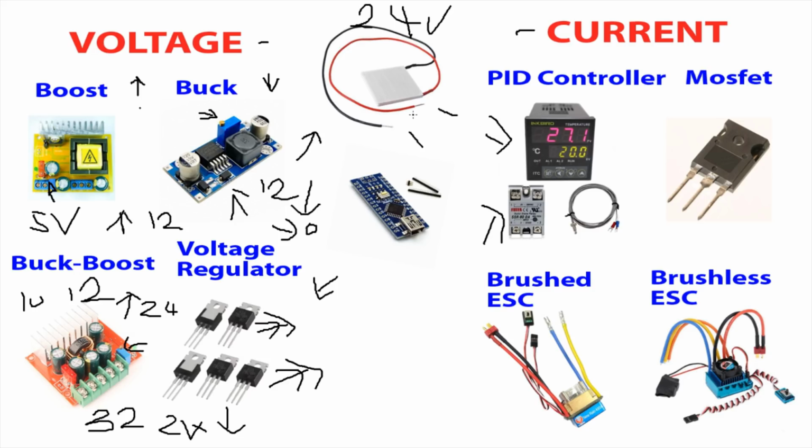Now if you've ever watched my video on TEC reliability, the TEC is capable of transferring heat even with the TEC off. A TEC is dissimilar metals glued together. Metals conduct heat, so with the TEC off, it will conduct heat. So normally you'll have your heat load here.